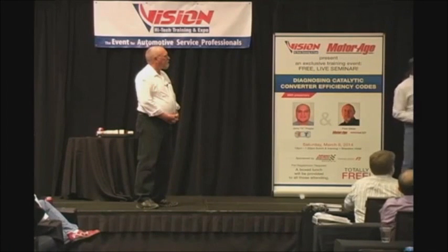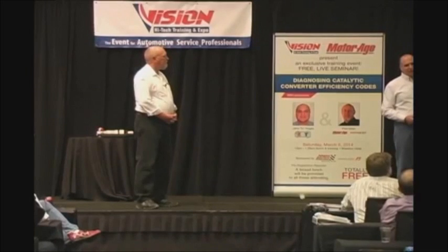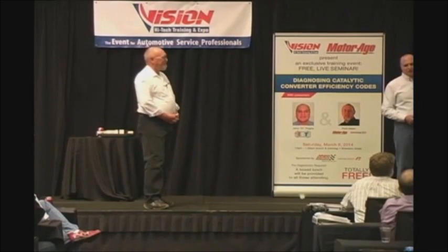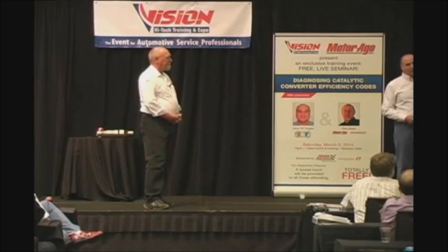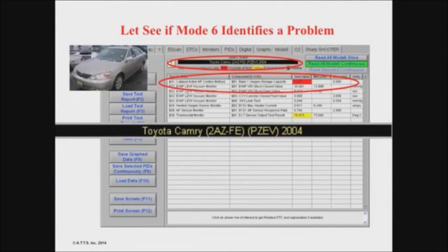Okay. Now, you know, the word that said oxygen. The guy who worked on this car, when he saw that, guess what he did? He replaced the air fuel sensor on his car, no lie. He called up the parts store. Of course, they didn't have it. He had to go to the dealer at the time. And they understood his lingo, oxygen sensor meaning an air fuel ratio sensor. So they sent it out to him. He put it in, and of course it didn't work. Okay. He got the same results.